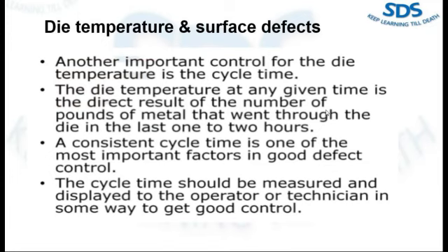So how do we know what activity is taking 1 second more? If we have differentiated the activity in a cycle time study, we can easily find out which activity is taking more time, and we can directly control that activity. So this is the way. I have seen many check sheets on the shop floor where they just write down 60 seconds. That's it. How will it help you?